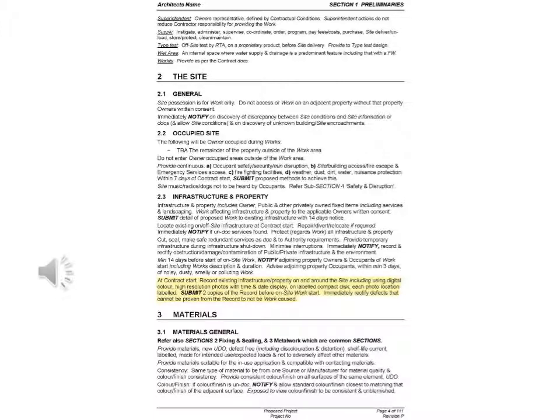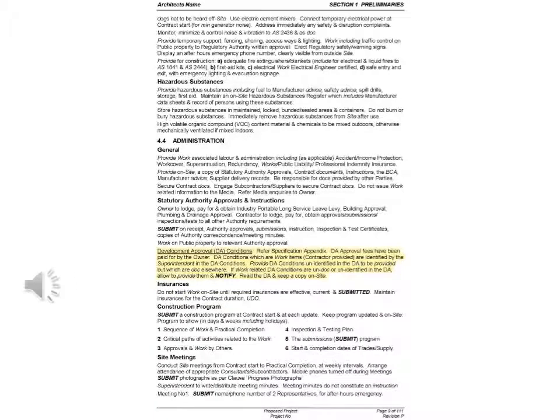Don't forget this is an overview where I'm trying to show you some main points. You can always download the sample preliminaries from our website for closer inspection. Moving down to the building work subsection, clause 4.4, development approval conditions. DA conditions contain contractor's work which, if not documented, result in variation. The conditions often present work unclearly, so the most effective way is the architect identifies, with a pen on the DA condition, the contractor's work. This is scanned as an electronic file and put in the appendix.